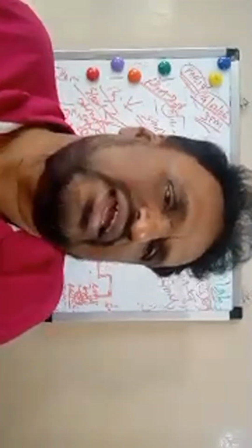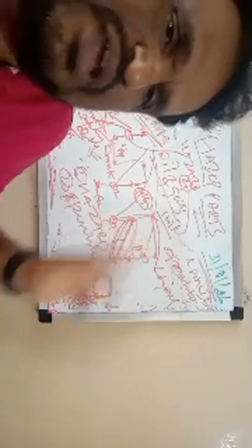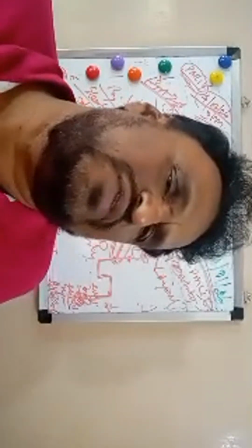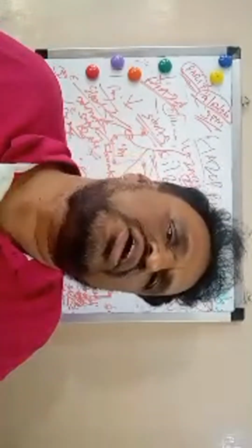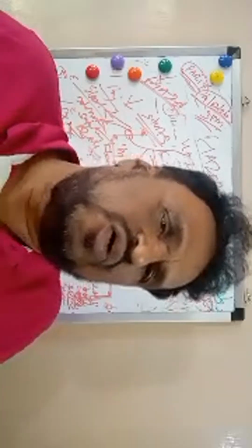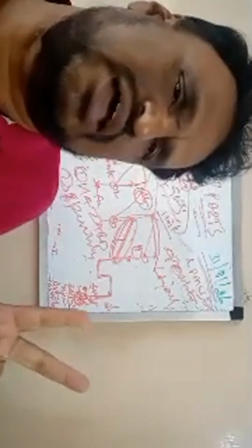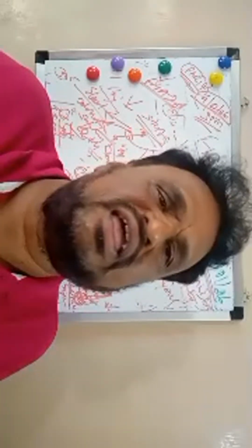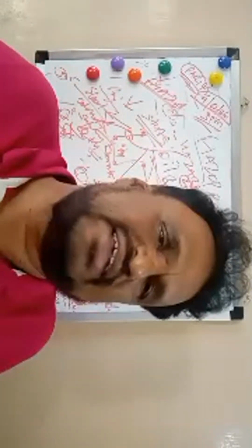they have a HAZOP team meeting. They will have solutions: where to rectify, where to correct it, how to correct it, what control measures we have to put before the operation. So here are the two issues for HAZOP. One is finding the hazards and making the control measures for the accidents.